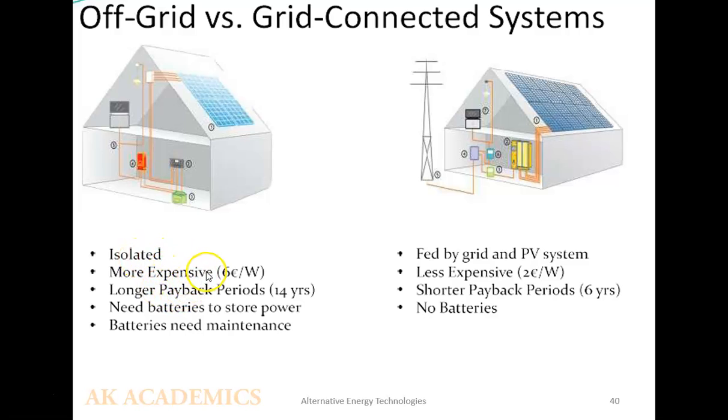It is more expensive because it has to have a battery incorporated into it, and incorporating batteries into a PV system means that we are adding storage to it, and when we add storage to PV systems, it increases the cost of such PV systems. Again, it has a longer payback period compared to the grid-connected PV systems. It needs battery to store power, and batteries need maintenance. So that means the cost of maintenance would also increase compared to the grid-connected system.